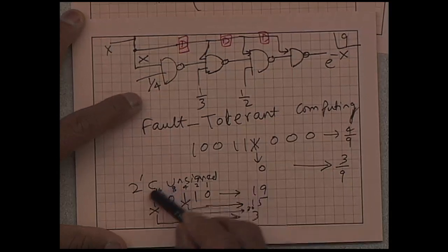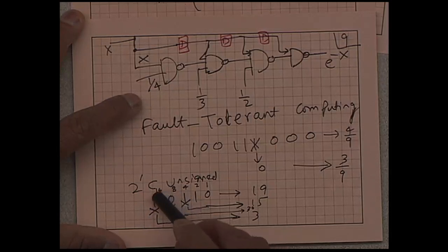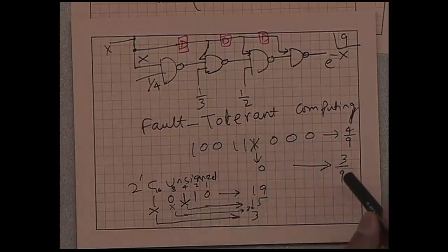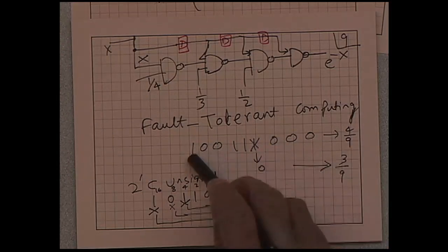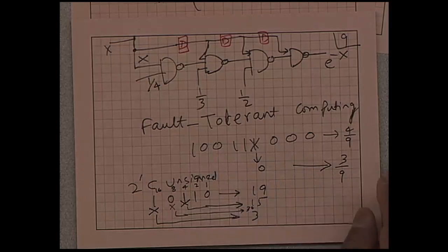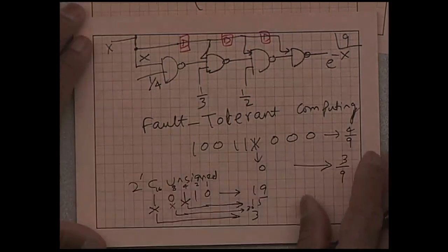So if any of the MSBs or more significant bits fail, that's changing the value a lot. In the unary case, it's just changing by a small fraction, 1 by the length. And that was one of the reasons why people became interested in stochastic logic and stochastic computing.